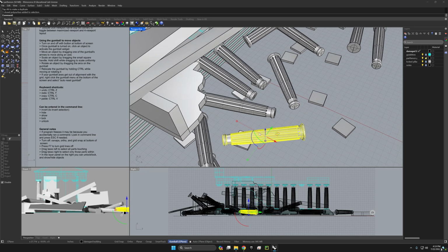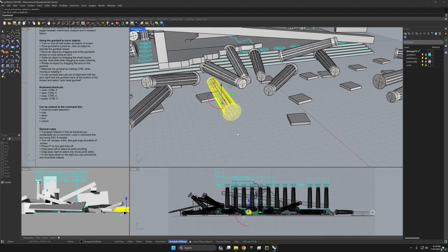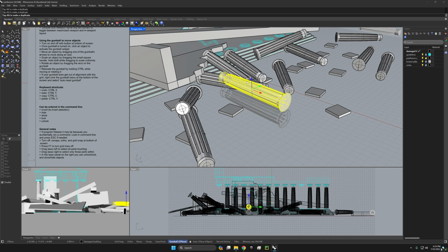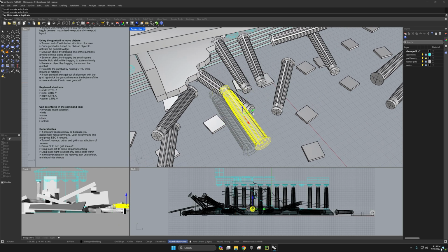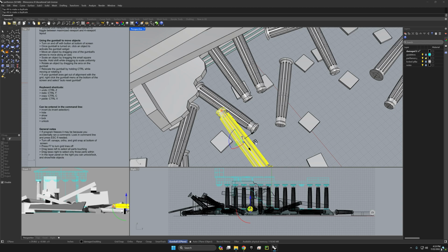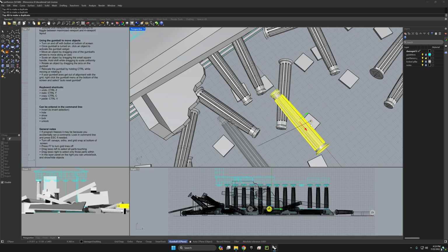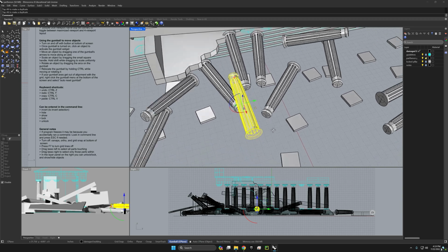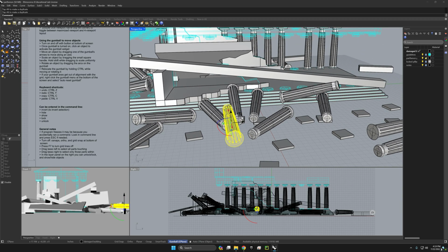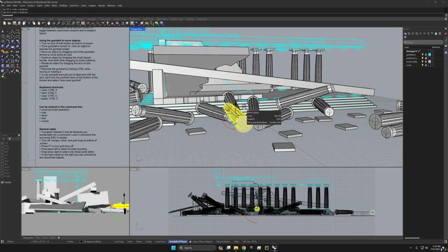If we grab one of these arcs, it will let us rotate an object. If we use the red arc, it's going to rotate along a different axis. If we use one of the arrows, it will move the object along a particular axis. Or you can see that little window pane thing right there. If we grab that, it will move the item along a plane. So right now we're moving along the XY plane. If we orbit down to the side, you'll see that a different one of those window pane things pops up, and we can use that to move the item now along the ZY plane.